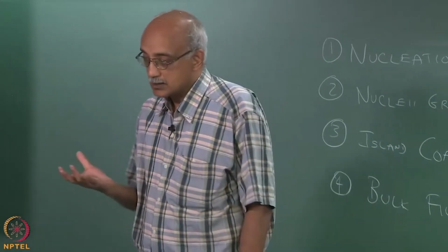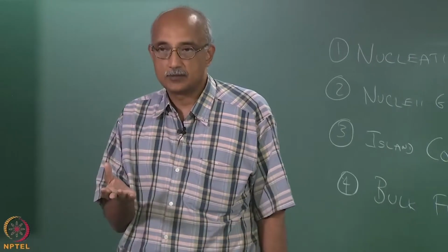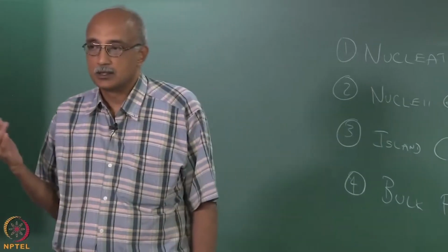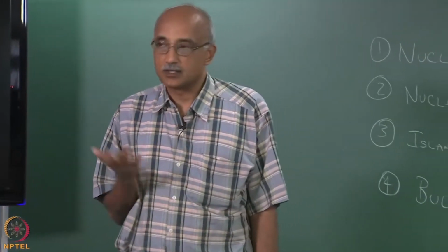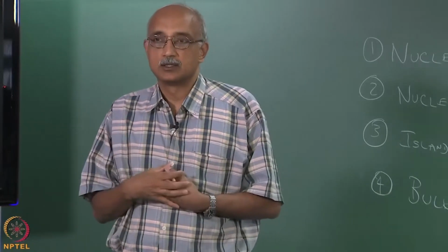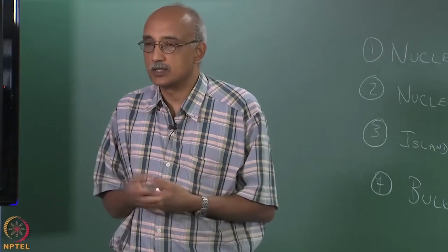Or in other cases, for example, if you have some impurity that enters your CVD reactor, for example, oxygen is frequently an impurity in CVD systems, because unless your CVD reactor is hermetically sealed, it is very difficult to prevent air from seeping in, which is mainly O2 and N2.